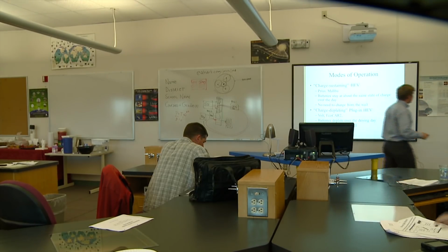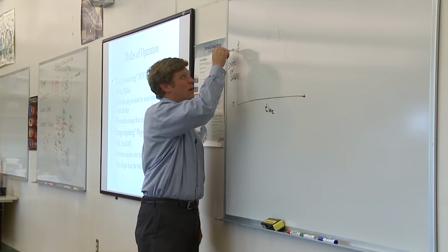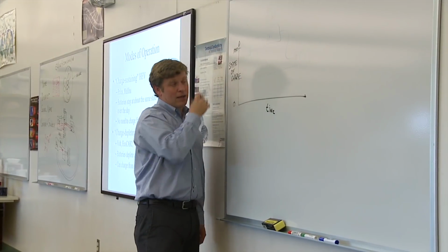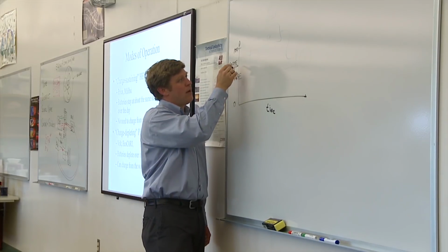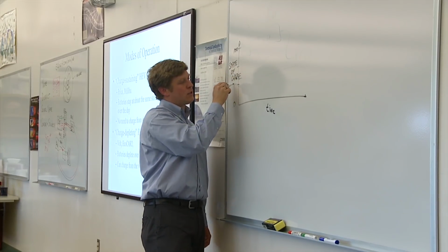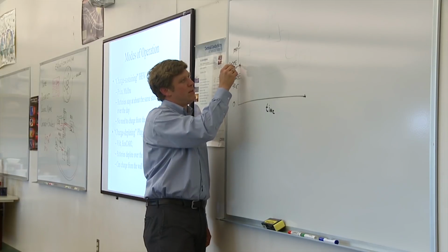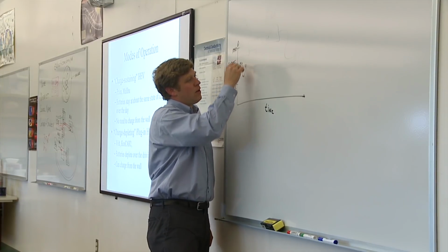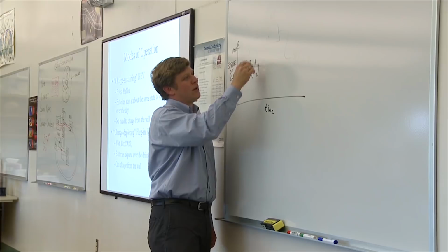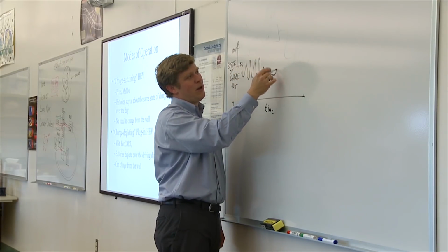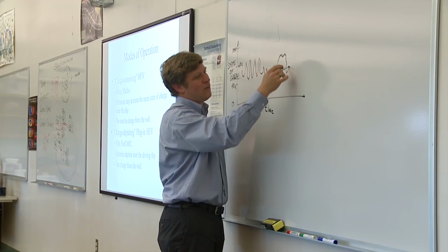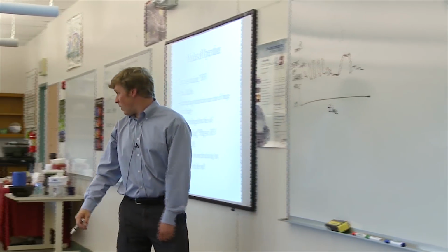It's not too tricky, but it goes between 0 and maybe 100% state of charge. For a conventional hybrid, for instance a Prius, that might vary over a day's driving between 40% and maybe 60%. So you'd be doing this kind of thing all day. You drive up the mountain, and it might get a little bit low, and you drive down the mountain, it might get high, and it would just do that.